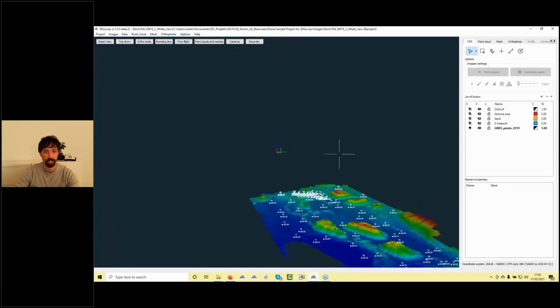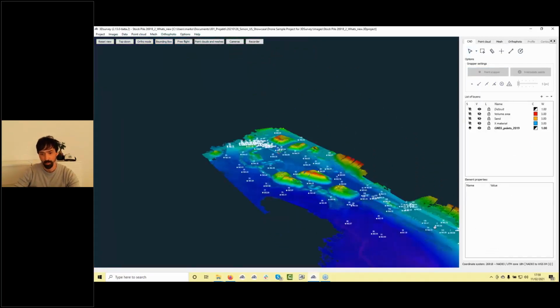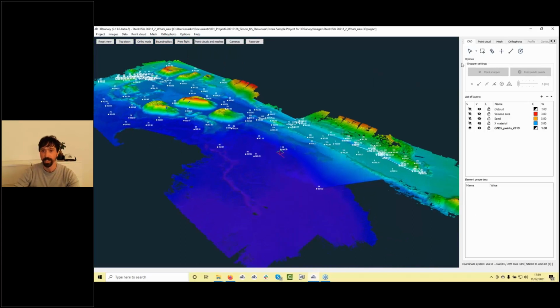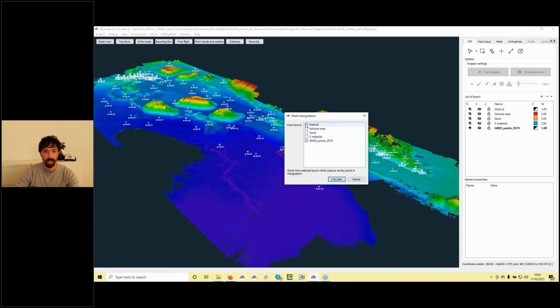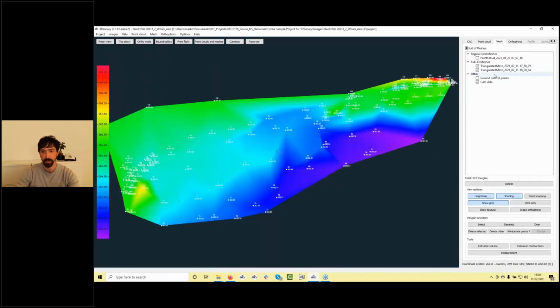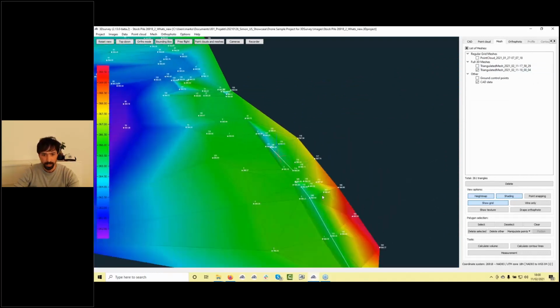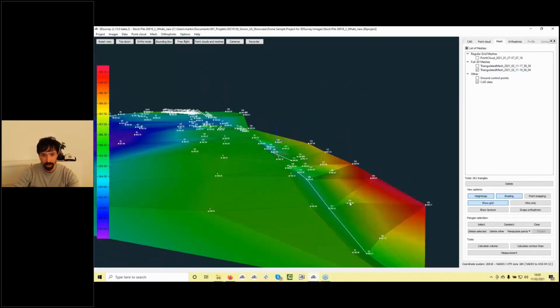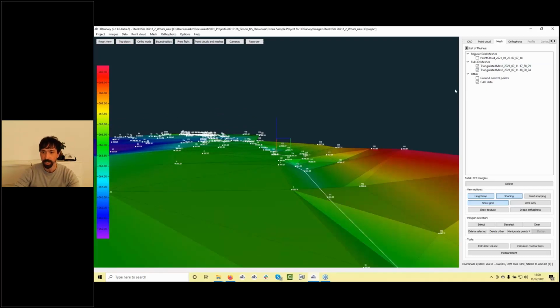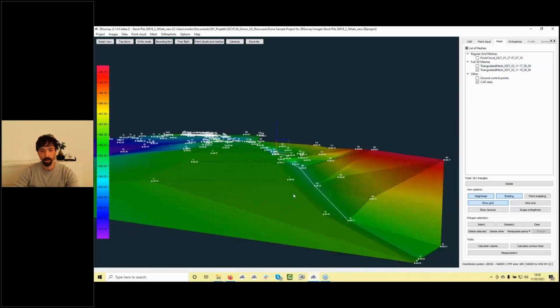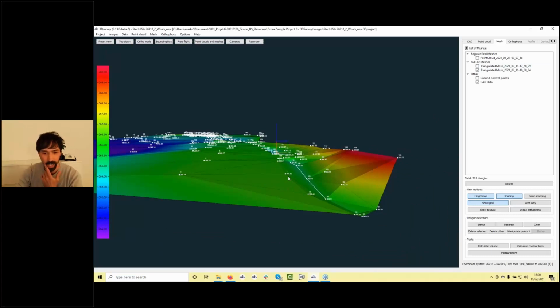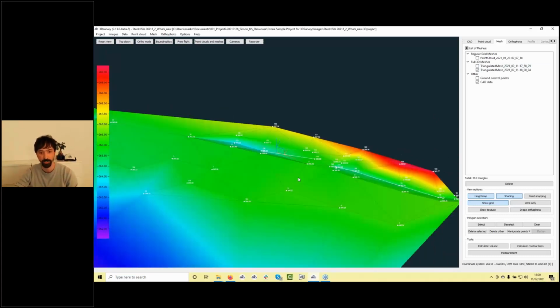So I actually create two break lines, and if I go again and do the triangulated mesh from CAD, now I have also those two break lines. Turn off the previous model. Let's see. Yes, it works much better. Okay, I would need to draw also here, but even now we see before how it goes here, the connection. So with the help of mesh calculation, with the break lines and points, you can achieve a perfect model.